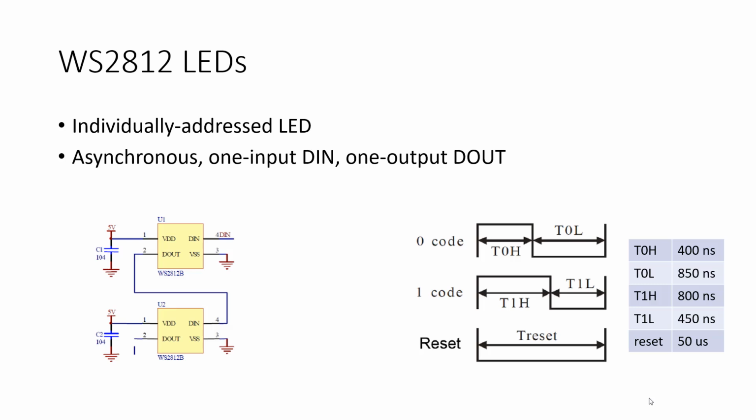If you program the colors on the LEDs, and then you go into this reset phase where you tell them, okay, I'm done, they will maintain the color that you programmed them with last. So they maintain whatever the last color is that you program them with, right? Does that make sense? But in order to reprogram the colors, you have to have at least 50 microseconds of this downtime, right?